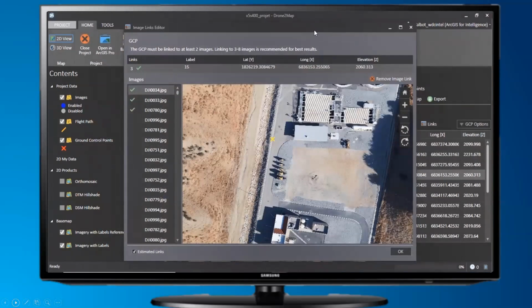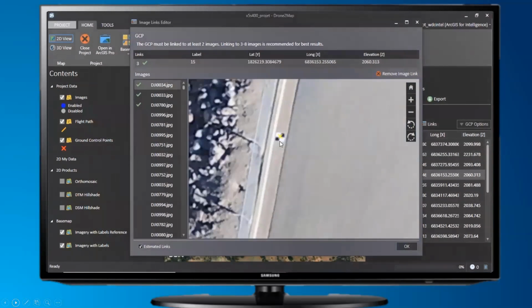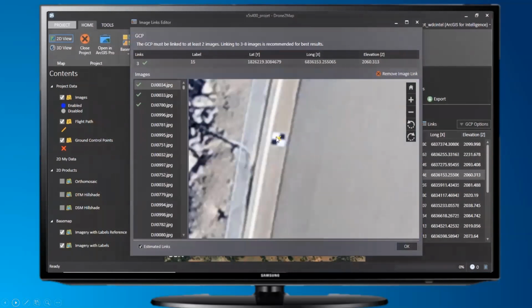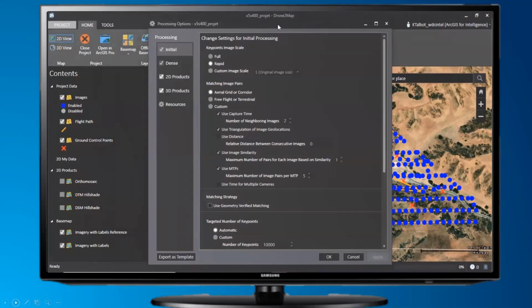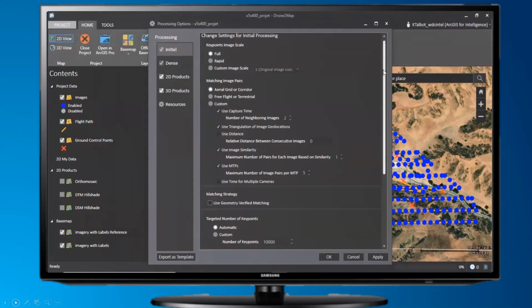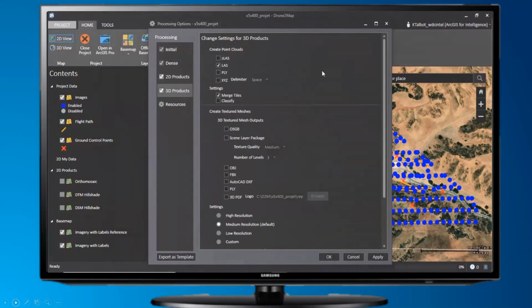And then this is the tool that allows us to bring in ground control points. So you see that X, that marks the spot. And so what I've done is I've told the computer that this photo is marked at that exact location. And that ensures true 3D accuracy of my products. So on different surveyed-in points, we've had accuracy down to 3 centimeters in 3D using drone and surveying-type techniques. So it's very powerful.